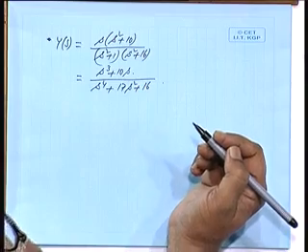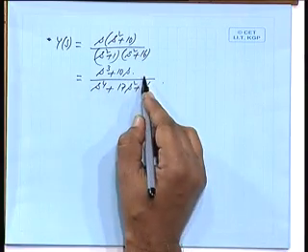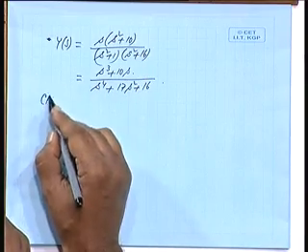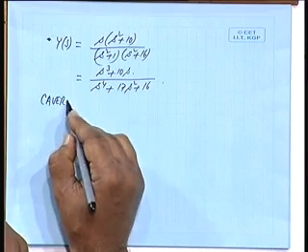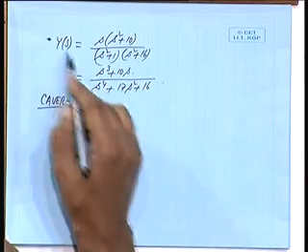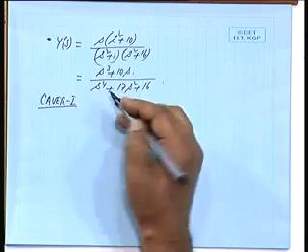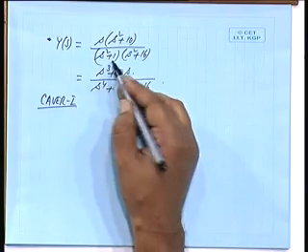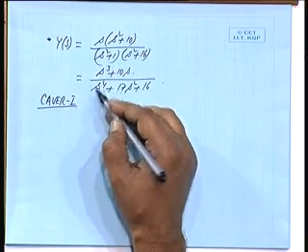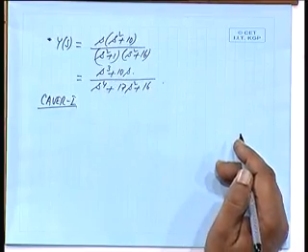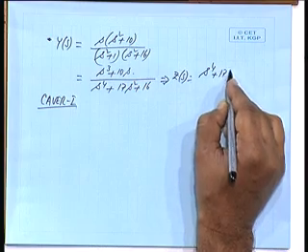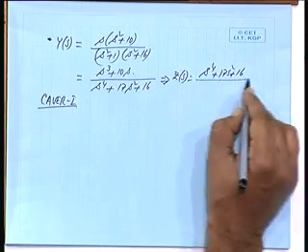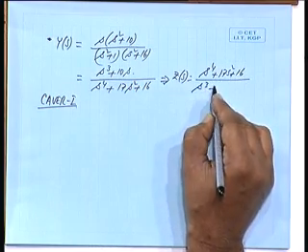Is it all right? So, they are all in descending order. So, in Cauer 1, this is YS. I should try to get S to the power 4 in the numerator, then only I can divide. So, this can be written as ZS equal to S to the power 4 plus 17 S squared plus 16 divided by S to the power 3 plus 10 S.